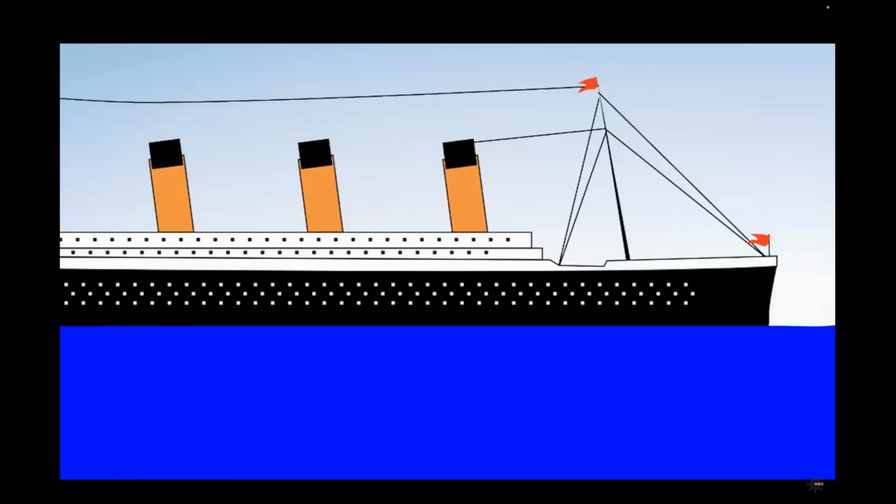As it moves through the water, a pressure wave builds up at the front of the ship. This increases the height of the water. The ship is pushing it ahead, but that water has to go somewhere. So what happens? It flows back down the side of the hull. It will keep flowing back down, forming this wave all the way along the side of the hull.